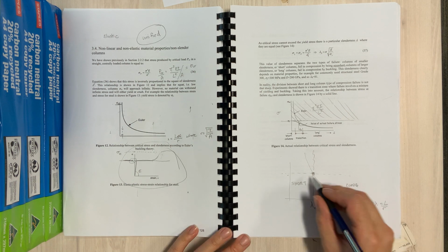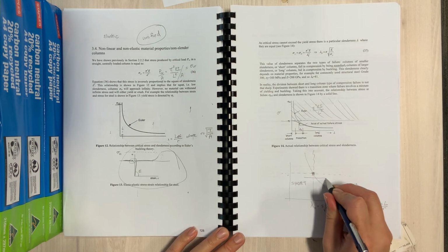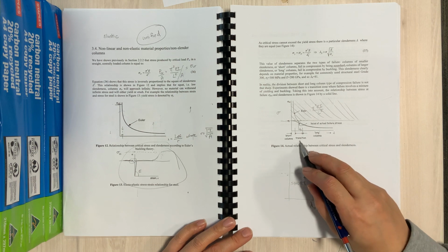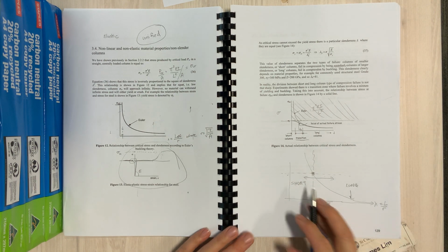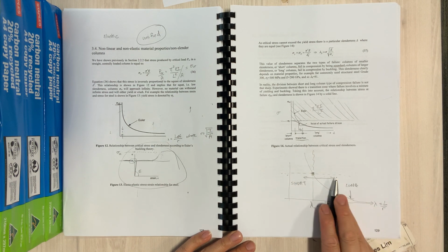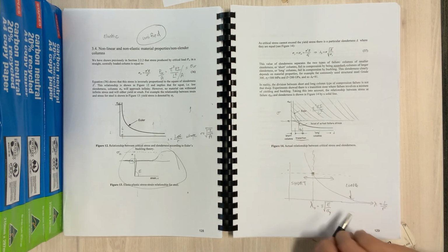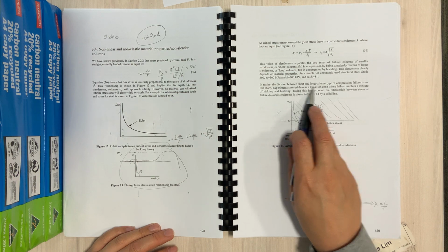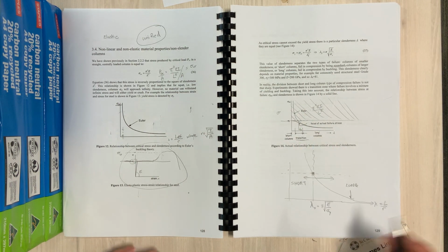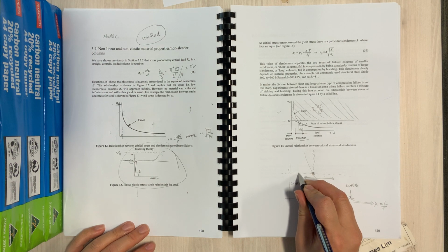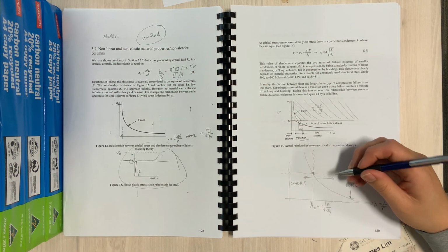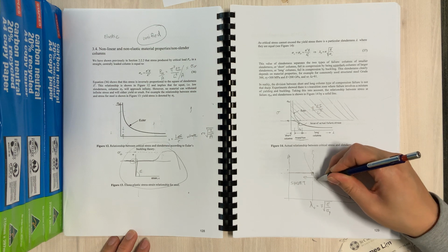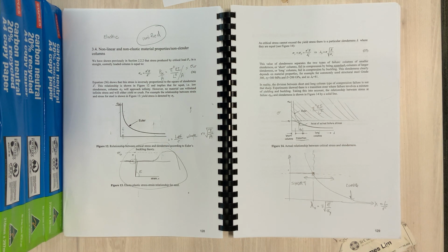And then in reality, you've got a transition zone between the short column and the long column, which is where things become interesting. Sometimes we call those intermediate, or here they call it transition. Something clearly is short on this side, something clearly is long here, and if you're not sure because it's around this area, we'll just loosely call it the transition. In reality, the division between short and long columns is not that sharp. Your buckling curve, which we've drawn here, doesn't just go there and then suddenly at that point go downwards. That's just not the reality of life.